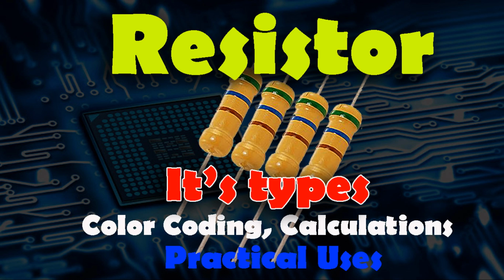Biasing circuits. Fixed bias circuit. Description. A resistor is connected between the base of the transistor and the power supply to provide a fixed base current. Advantages. Simple and easy to implement. Disadvantages. The operating point can vary with temperature and transistor beta (β) variations.